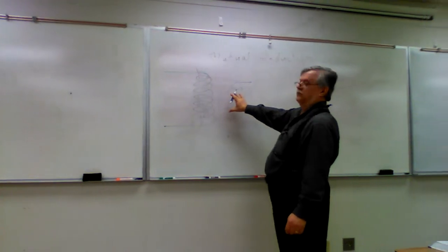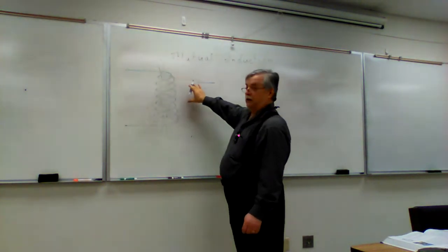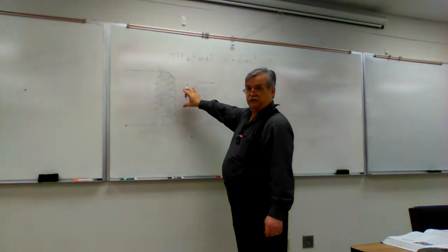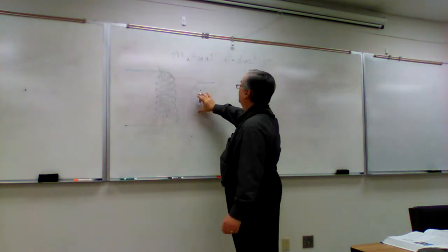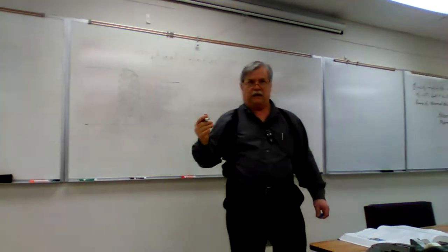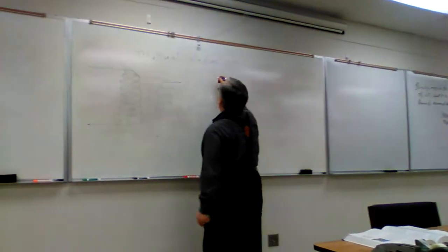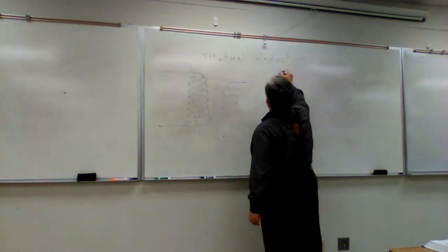When these magnetic field lines expand over here, depending on however much flux gets to this coil, it's going to induce a voltage over here. We mathematically looked at how to calculate the amount of EMF induced in a coil by a magnetic field.